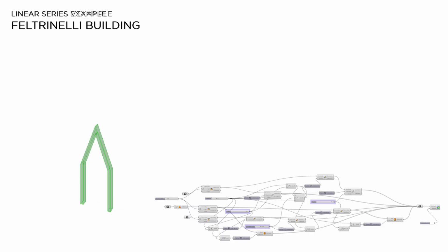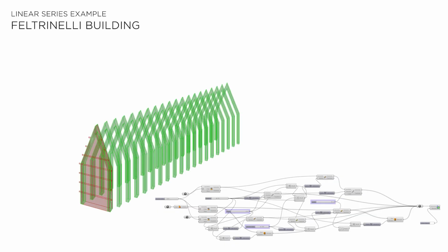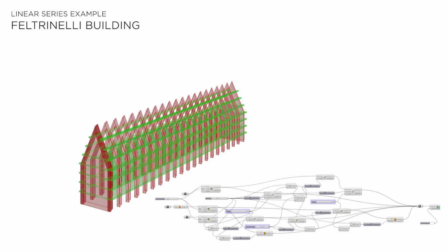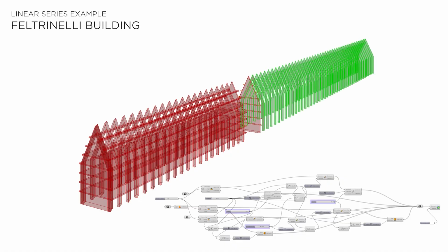As an example of a linear series, we propose the Fondazione Gian Giacomo Feltrinelli building in Milano by Herzog & de Meuron. The logic behind the algorithm is the same as the one proposed, with the difference that the structural elements in elevation in this case were not defined by points, but by closed profiles, and that these were previously rotated before their repetition in series. While for the horizontal planes, these were simply extruded.